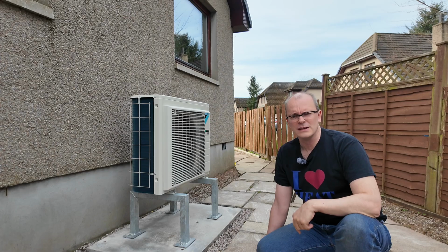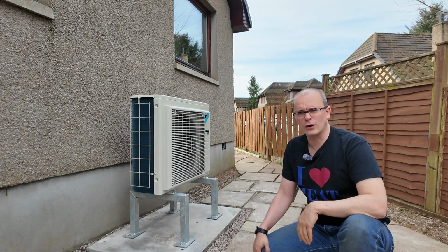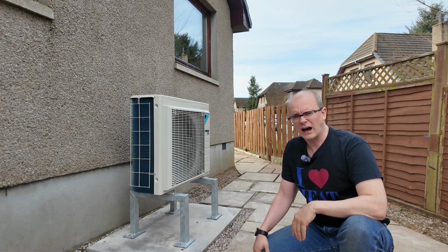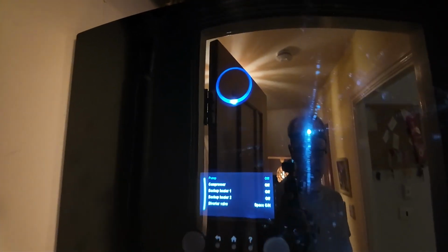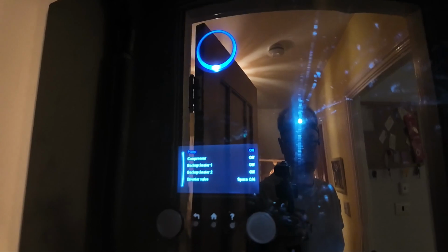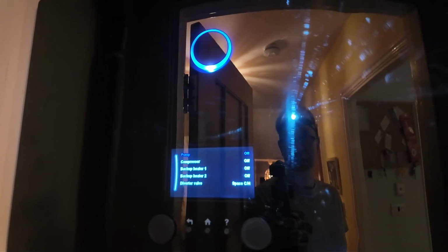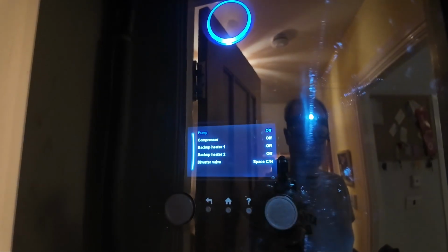So one of the other things I noticed overnight was some odd noises coming from the heat pump when this was starting up in order to supply hot water for my tank. Let's take a look at what the symptoms are. So yesterday I heard some knocking sounds coming from this, and this was a situation where the heat pump was starting from cold. Very odd situation. The compressor started before the pump. So it's now 11:30 at night, and we're going to see what happens again.